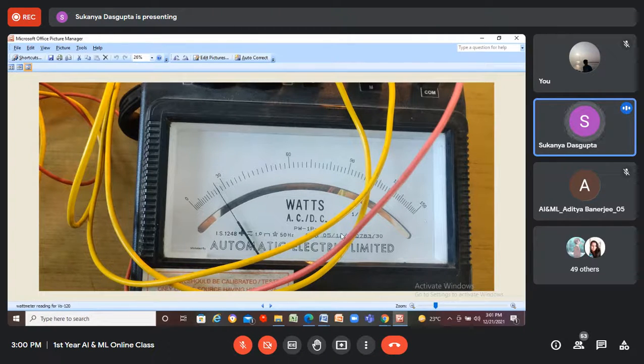of this wattmeter. See, it can be used for both AC and DC. This is basically the advantage of electrodynamometer type instrument. Both these symbols are available. See, a sinusoidal symbol and this straight line or constant. This signifies that here voltage is constant, and this sinusoidal signal signifies that this can be used for AC circuit. Also 50 hertz is mentioned. One means unity power factor.